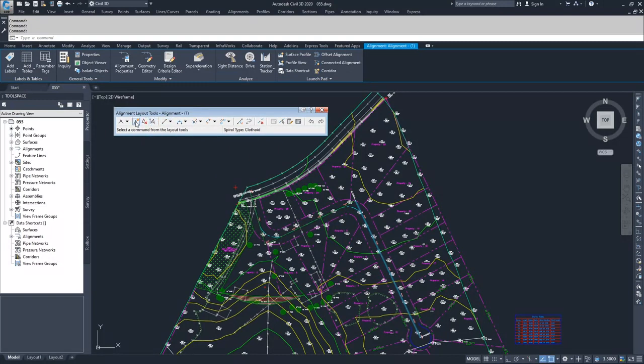These options will either dissolve that point of intersection and move the line between the existing start point and that point of intersection, or add a new one, which changes the tangency between two existing points of intersection. If you break a point of intersection, it's going to get rid of the links between them. So if I broke this point of intersection, it would remove the two links between that point and this point. We're not going to deal with those.